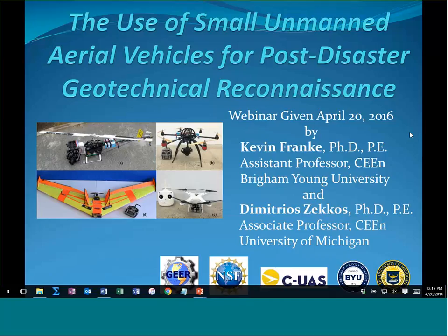Yes, so I think these are among the decisions that you have to make at the end. You're going to have a specific camera that has a specific resolution, and for that specific camera, if you fly very close, you'll get high definition data. If you fly far, you're not going to get as much. And so many times when people ask me something like that, I will say, okay, what are you trying to get? Because if you're trying to get a 1 centimeter wide crack and you fly 300 meters above, you may not be able to see it.